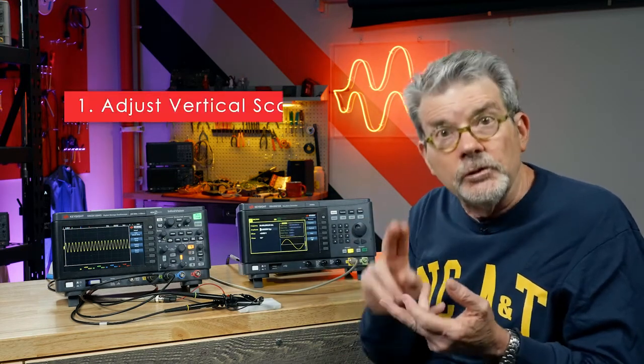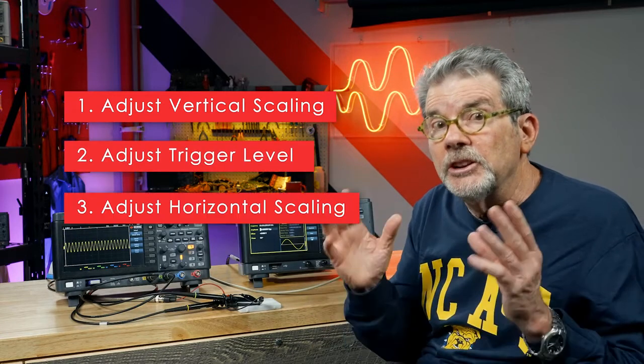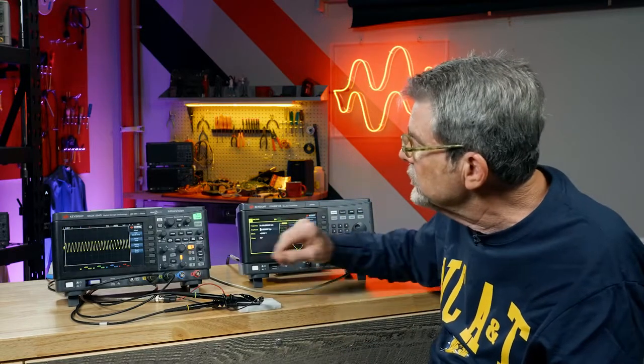Now, after pressing default setup, there are 3 main things you need to adjust: the vertical scaling, the trigger level, and the horizontal. So let's take a closer look at the front panel over here, and those three adjustments are in 3 sections of the scope.